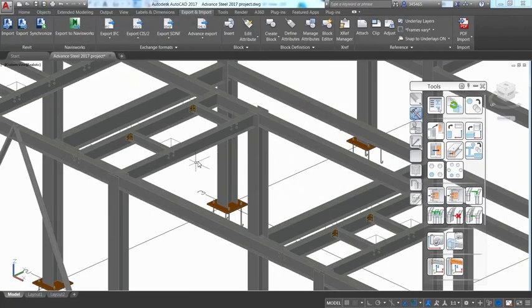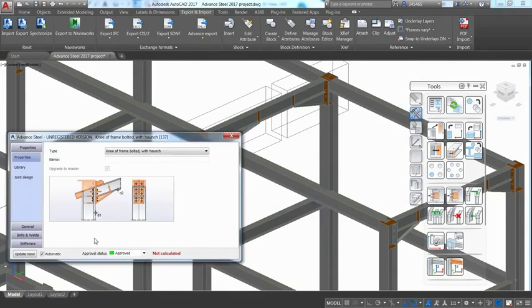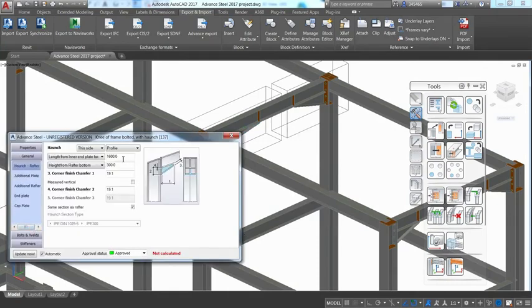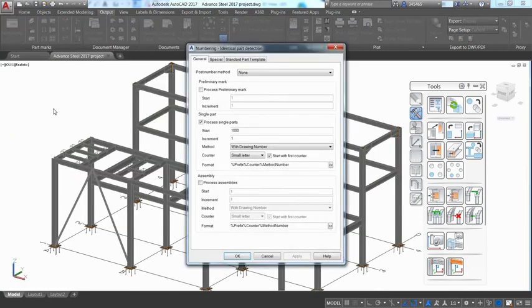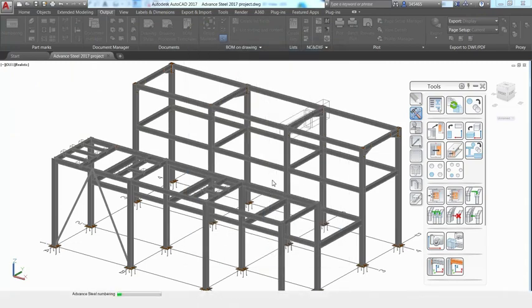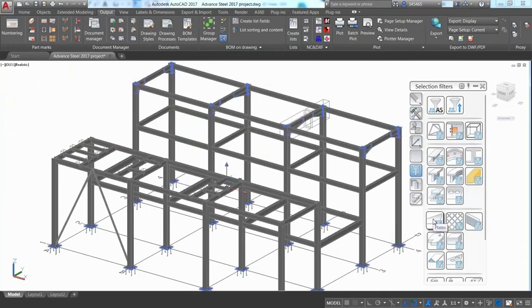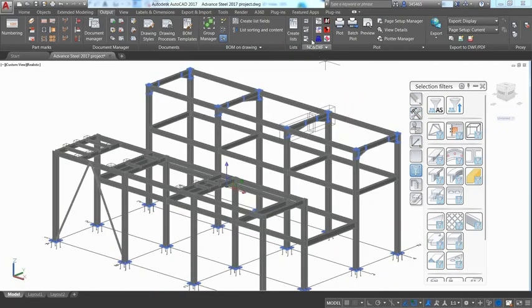The synchronization dialog provides details on what has been changed, such as the location of one of the beams or the approval status of one of the steel connections. Once you apply this modification, you get an Advance Steel model which contains up-to-date steel connections while keeping them as intelligent parametric connections. Advance Steel offers tools to number the model automatically based on user preference.